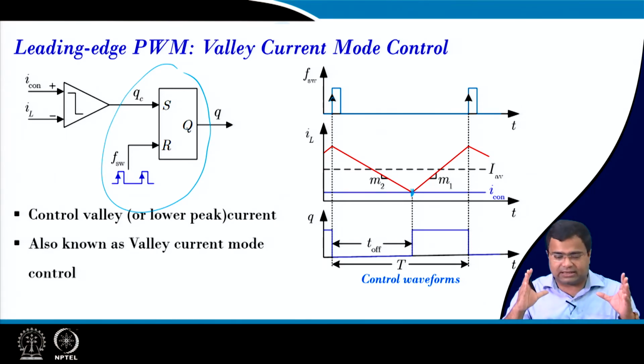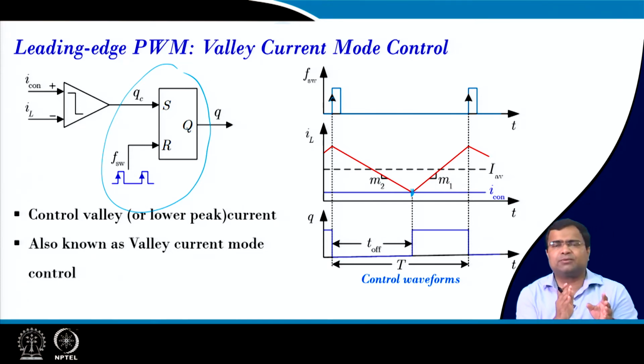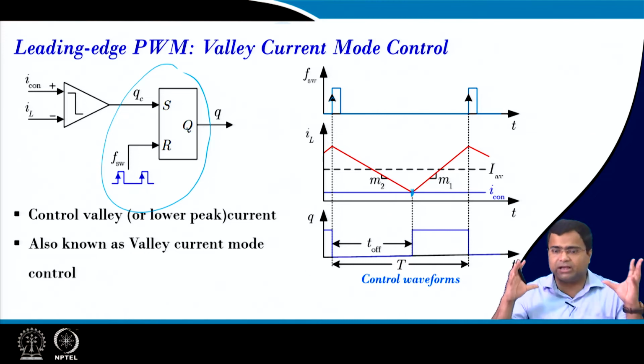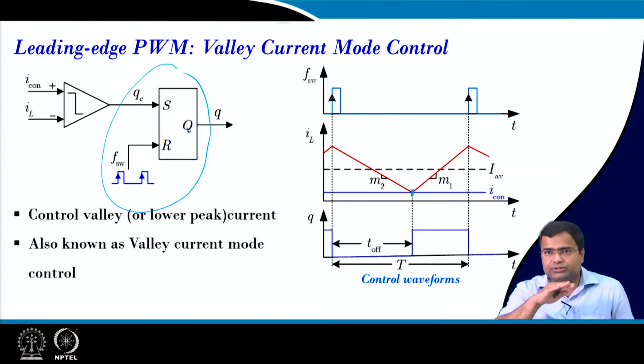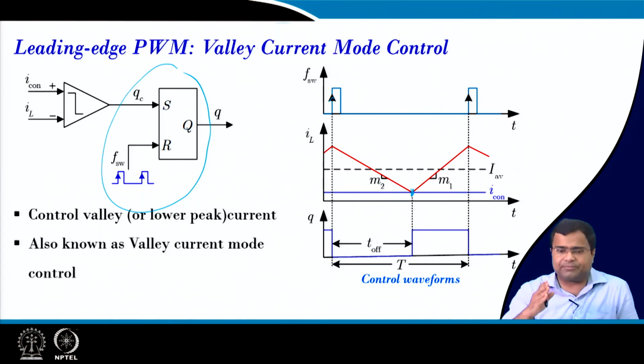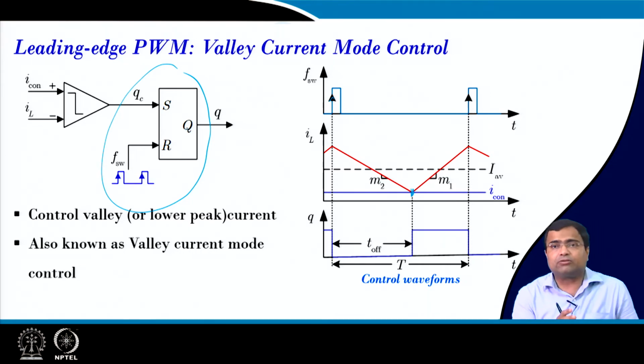And we have also discussed that in peak current mode control, the inner current loop is generally stable if the duty ratio is below 0.5, but under closed loop, even slightly lower than 0.5 the closed loop system can be unstable. But if we just use a constant current reference, up to 50% or just below 50%, peak current mode control or trailing edge modulation will be stable.